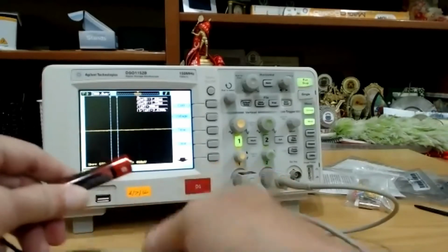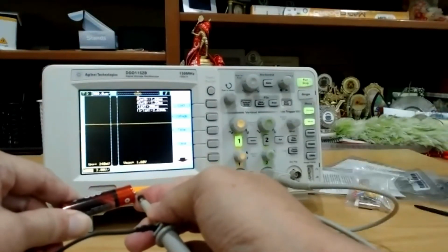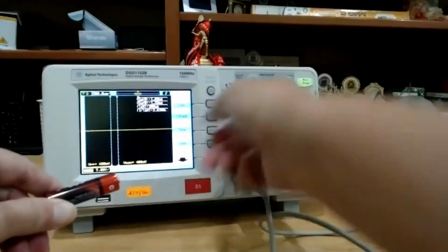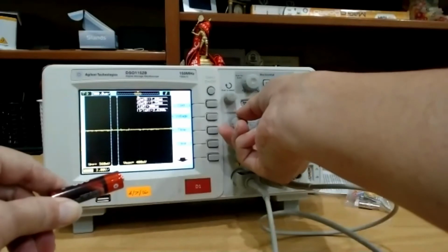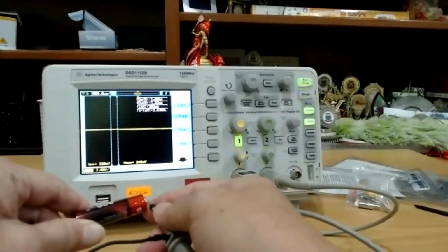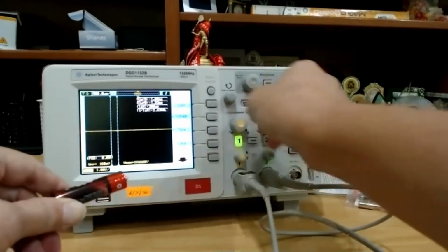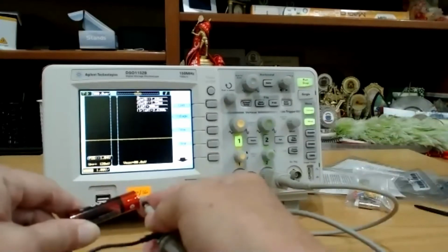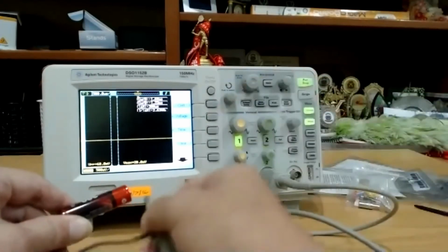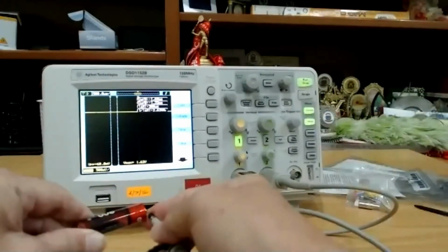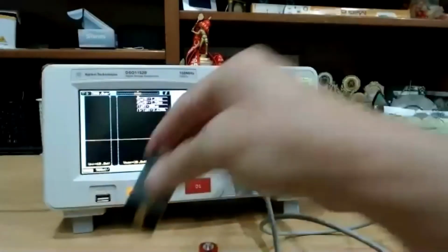It's not so accurate, the scope, unless you change your scale. If you change your scale too small, then it may not measure for you. You have to magnify the amplitude. Then you can see this is about 1.52, 1.6. You amplify it further. See, about 1.68. Amplify further. Okay, about 1.62. So you can use the scope to measure your battery this way.